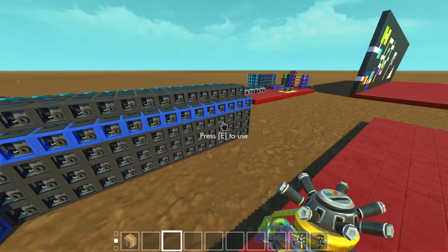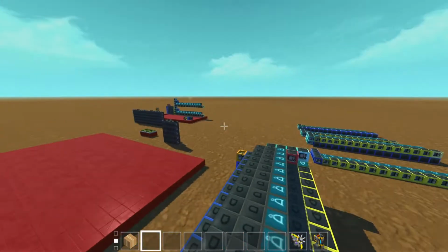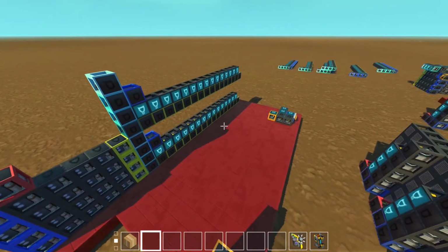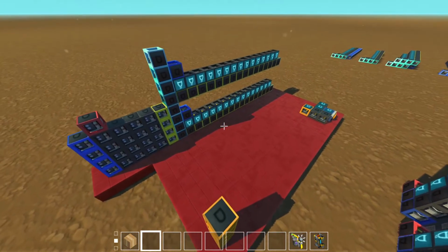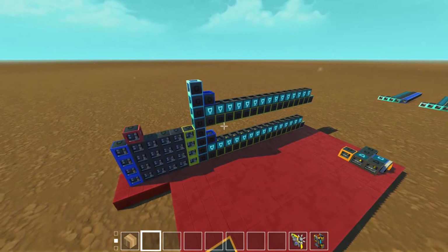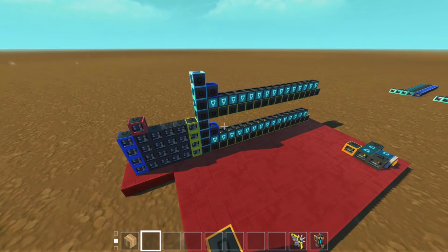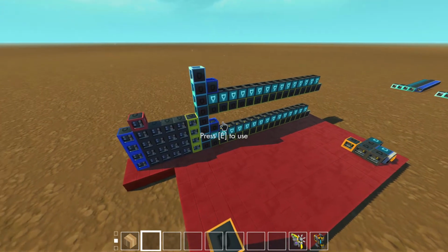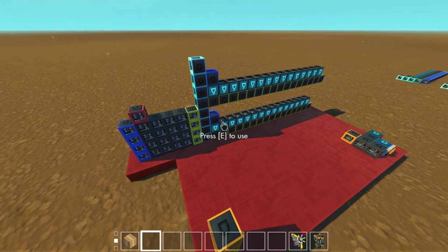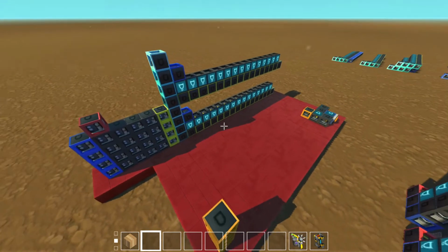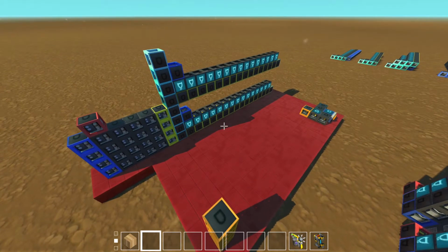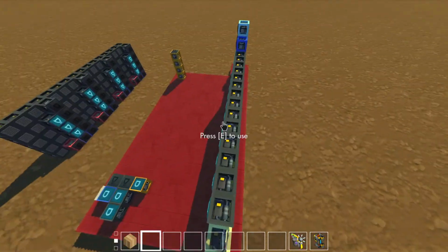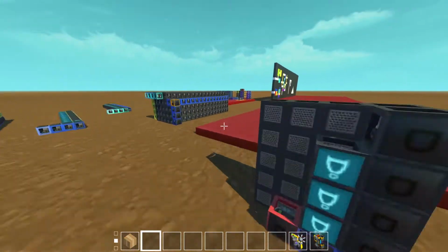I already have a very good feeling about this whole new paradigm. So the state machine concept works a lot better than the old control unit concept that I had before. This is much more flexible and is even reprogrammable if you're interested enough to alter the hardware. What would be even more interesting is one that uses an EEPROM, where you can electronically reprogram the ROM so that you can actually have a state machine that you can reprogram at any time, which I think is pretty great. Some may disagree.